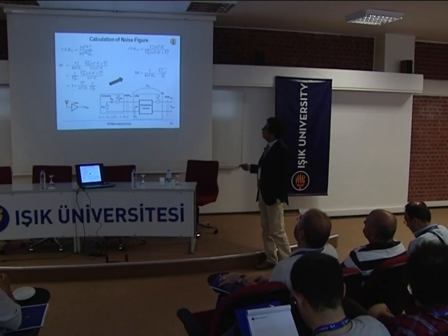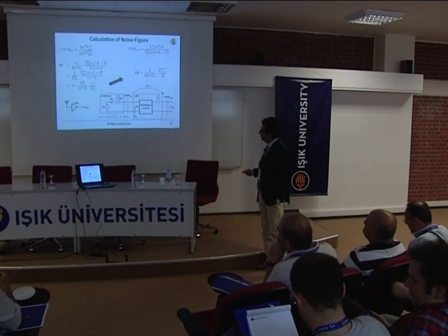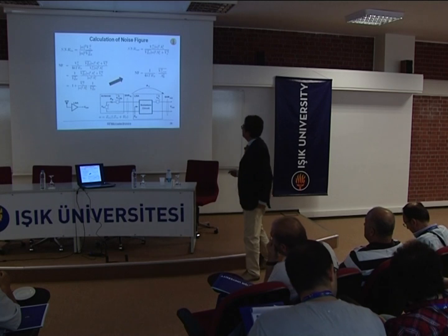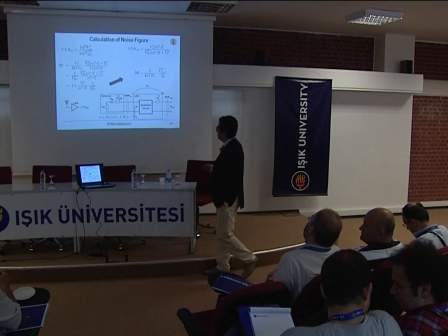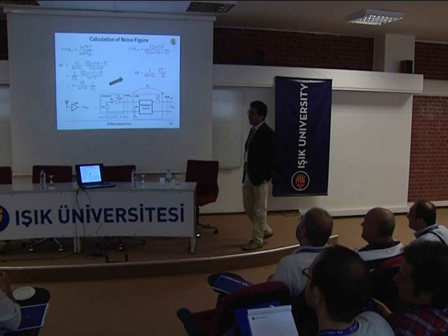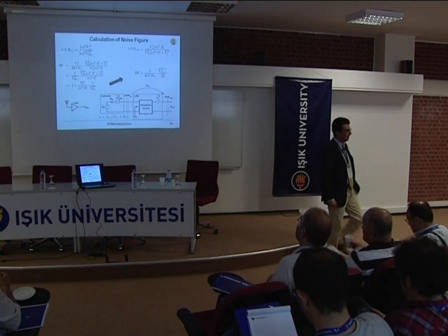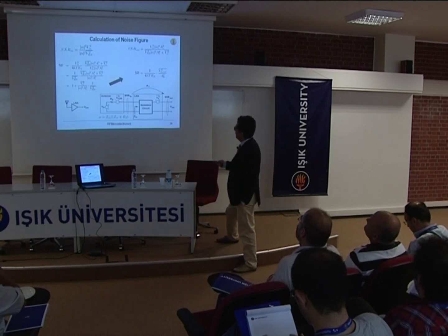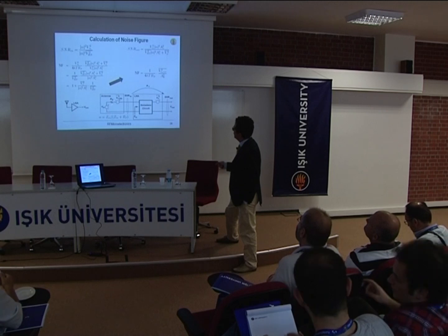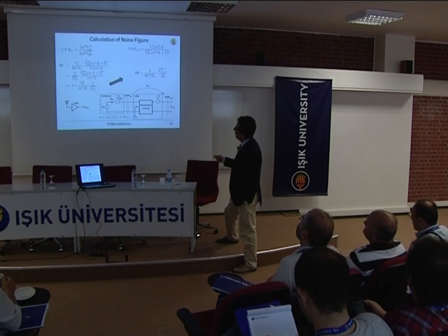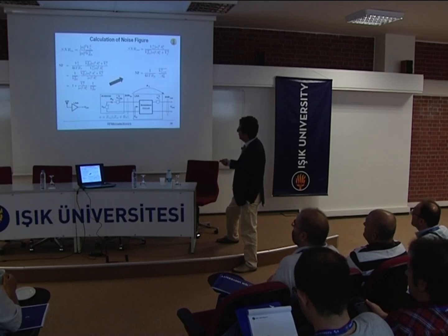So the input signal to noise ratio, if we have an input voltage source VIN and we assume that the noise is due to the source resistance of the antenna, so we call it V square N RS, and is given by 4kT RS, it's thermal noise associated to the resistor, we can say that this is the signal to noise ratio, Vin square over V square RS. You see multiplied by alpha square, where alpha is the partition at the input, made of the input impedance and the resistor RS.